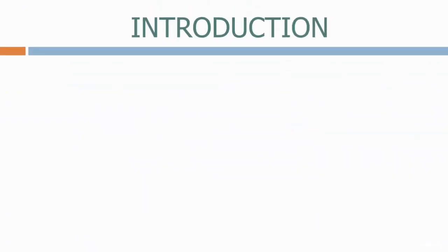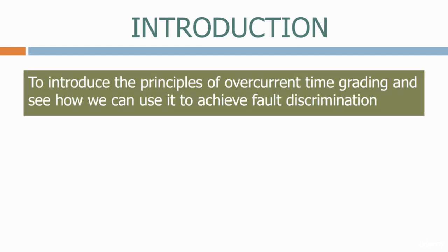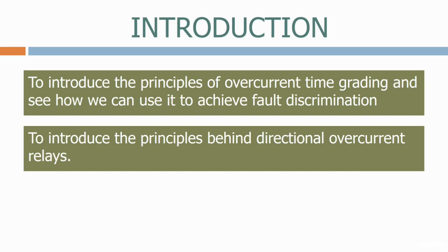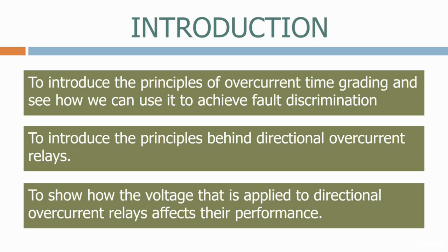The aims of the course today are to introduce the principles of overcurrent time grading and see how we can use it to achieve fault discrimination. To introduce the principles behind directional overcurrent relays. To show how the voltage that is applied to directional overcurrent relays affects their performance.